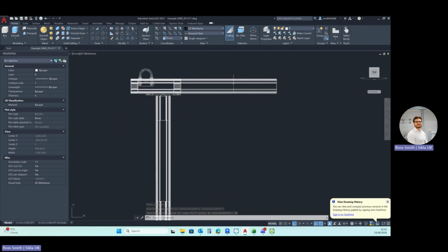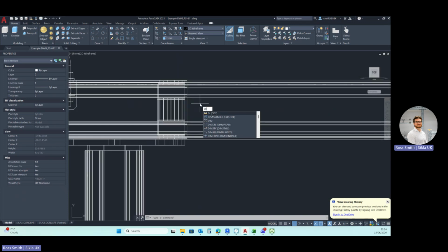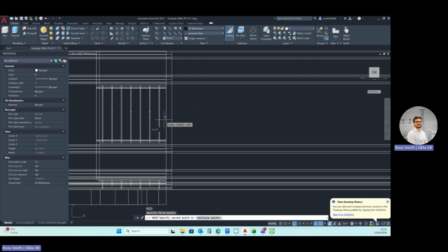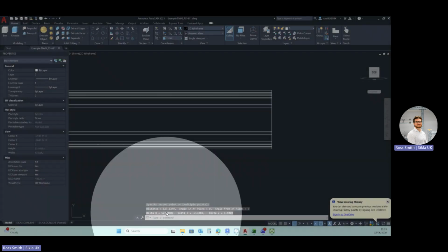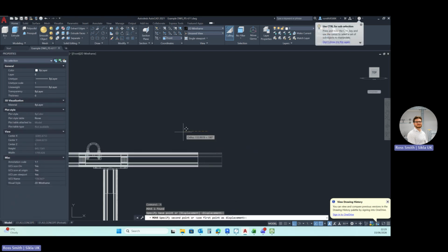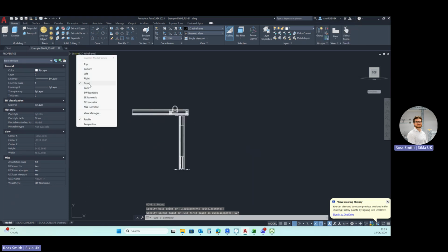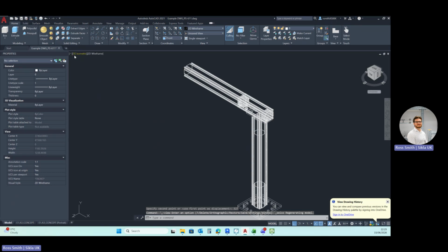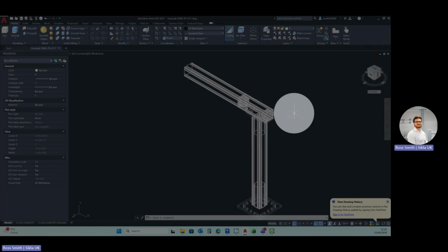Now, I actually want this beam section to be moved over this way. So whilst you're in this, this isn't a lesson in AutoCAD, but let's just see how far I need to move this along. So we can see 527, let's say we need to shift this left or west, 527. Okay, and then look again in south east isometric, because if it wasn't obvious, this item is relevant to the coordinate system you're modeling in.